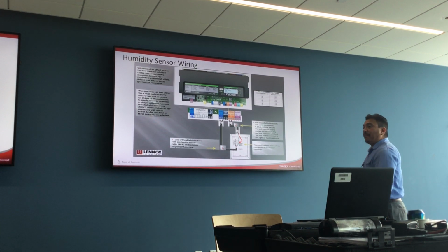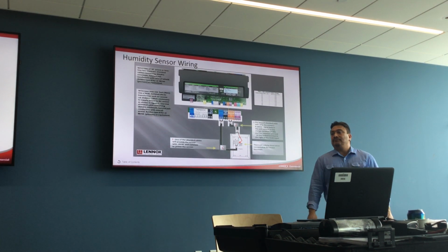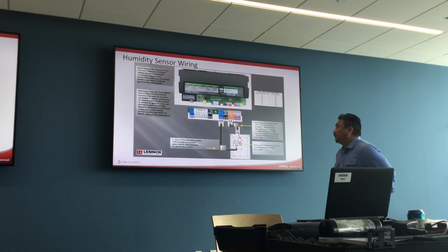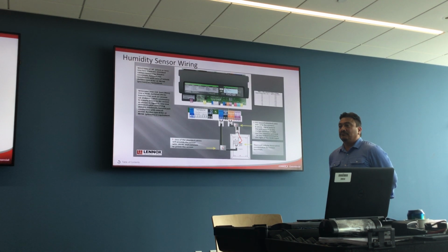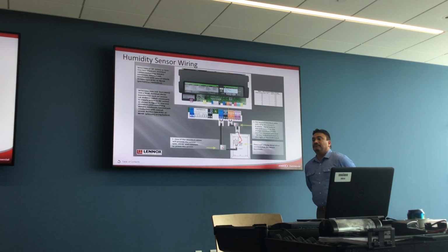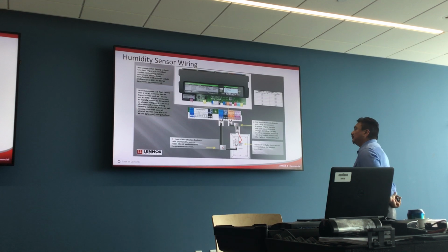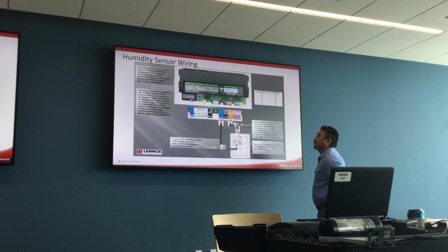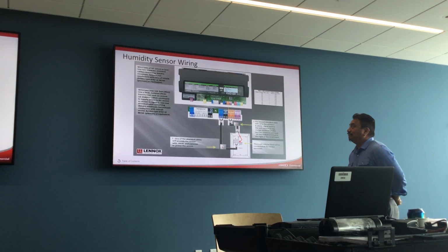Part of the reason this is in here is because that 17M50 sensor, you'll probably find some of those sitting in the blower section of some units. They get shipped and never installed. Typically where we ship those is in the blower section, and they're still in boxes, never been installed. And Humiditrol will not work without that sensor.